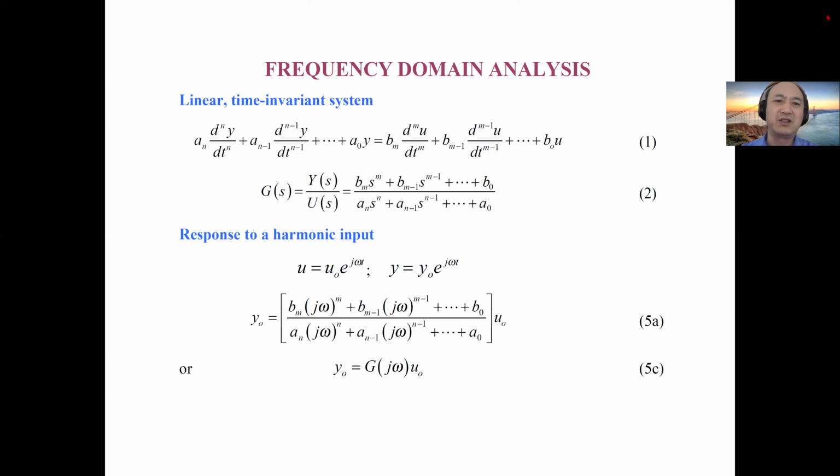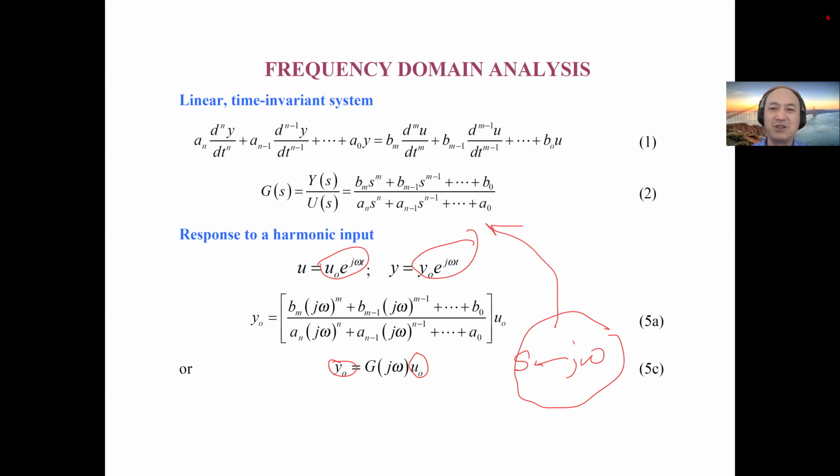So basically, for a linear time invariant system, you have a transfer function like this. Your input is a sinusoid, and the output is also a sinusoid. And the input-output magnitude is connected to G(jω) here. That's why you need G(jω), when s is replaced by jω. How many of you ask the following question? Why do we replace s in here with jω? I suddenly can talk about frequency response.